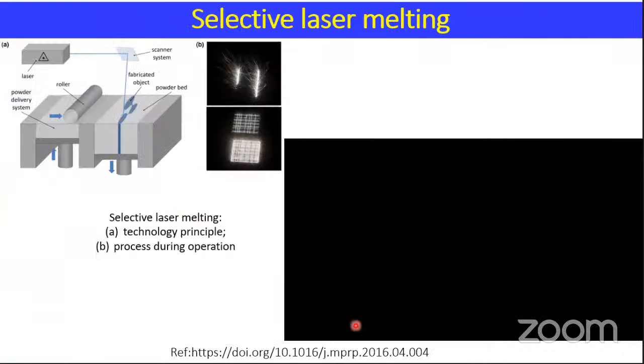And this particular technique, selective laser melting, as I mentioned in the first slide when comparing with conventional manufacturing processes. This is more for producing metallic components, and primarily laser sources are used. And this is the powder bed, and then the laser scanning happens, and then the part prints layer by layer. You can maybe understand more from this video.